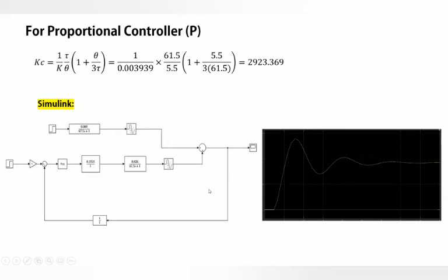So as you can see, the setup for the Simulink, we have the P controller, the controller gain, the transfer function to show how the valve responds, GV, the transfer function to show how the process responds, GP, the delay, and the GD disturbance, and this is the GM. This is also the scope to look at the response. So after running the Simulink, we will obtain this response.